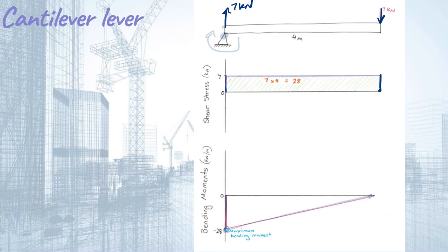So we have a beam that looks like that, and that'll give us a bending moment diagram. Basically it just goes down and then a line like that across there. And your maximum bending moment, of course, will be where the only support is, because you're not really going to have a moment force acting at any point other than where it's attached to the wall.